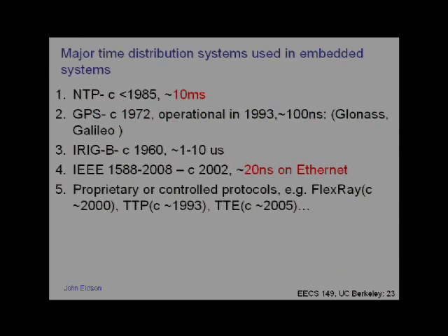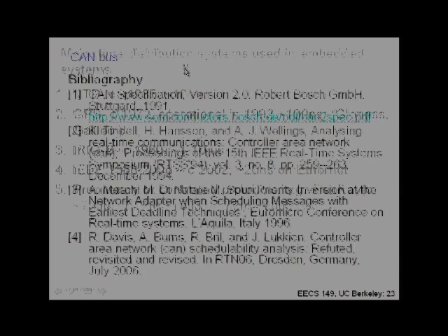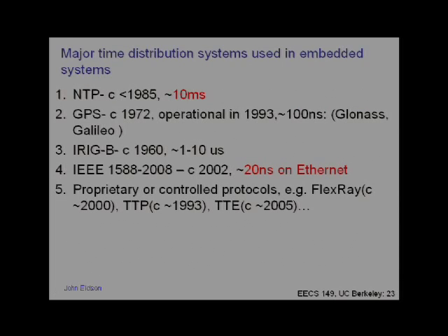Okay. So one of the things we talked about in FlexRay, which is becoming really important for embedded systems, is clock synchronization. And this is a topic that's been studied a lot. So just commodity computers on the internet, they're synchronized using NTP. Right? Many of you might have heard about it or read about it. The synchronization fidelity, though, is not that great. So it's of the order of a few milliseconds. But for a lot of embedded applications, you need much smaller synchronization skew, right? So of the order of nanoseconds. And that's what IEEE 1588 was geared towards.